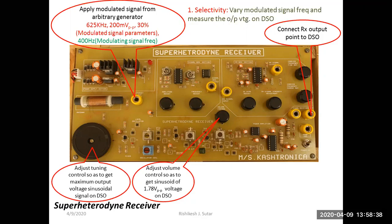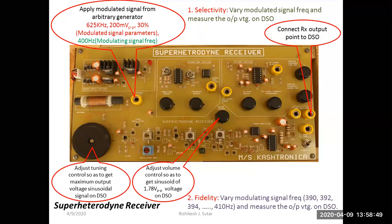Now the next characteristic is fidelity. In this fidelity you have to vary the modulating signal frequency and measure the output voltage on the DSO. Here also we can take 3 to 4 readings below 400 hertz and 3 to 4 readings above 400 hertz frequency, and you can measure the output voltage on the DSO. You can plot the graph of output voltage on the DSO versus modulating signal frequency.